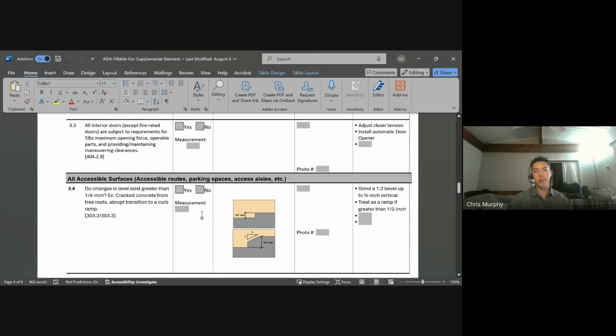If it's located between 27 and 80 inches, a blind student wouldn't be able to see it and could run into it. If it's treated properly where there is something underneath it, the object itself could extend below 27 inches, that would be considered compliant as well. But you'd really just have to put yourself in the shoes of somebody who can't see and try to understand, is there any obvious way to avoid this, or am I going to hit this if I can't see it?